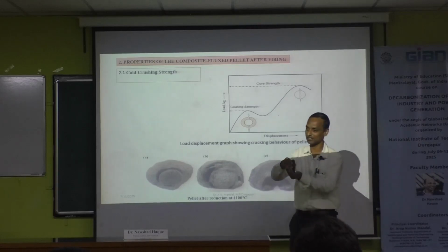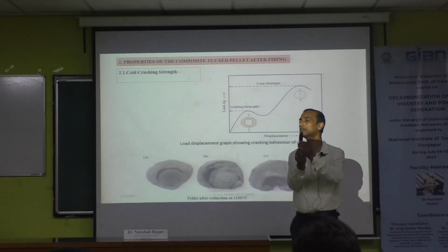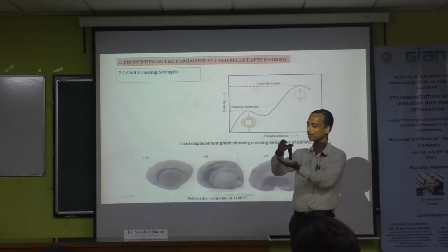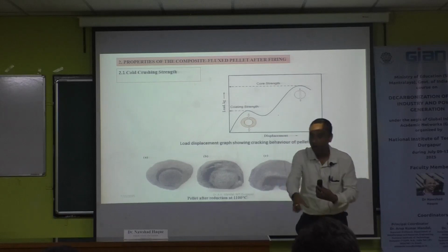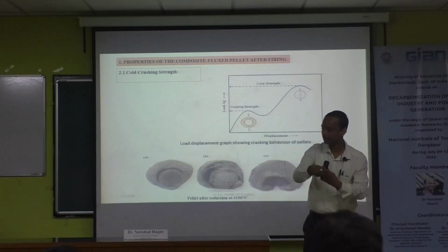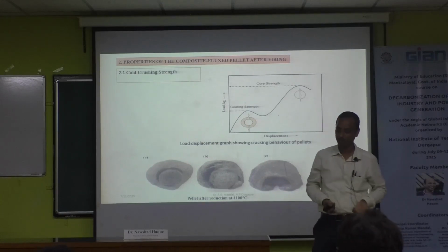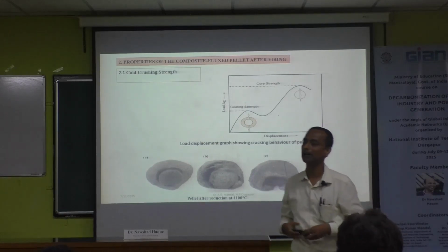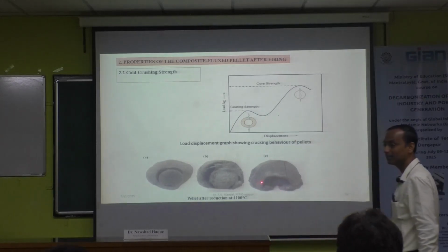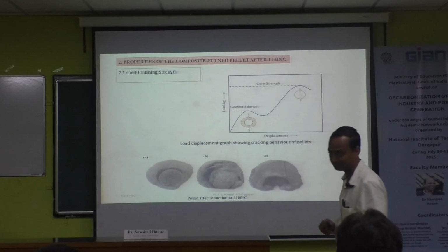The pellet was in this position. At the bottom portion, we observe the material is eroded, and it produces the slag. Because in stationary condition, the FeO content will gradually dissolve in the slag, then puncture happens at the top. Therefore, with higher basicity, we propose another method.